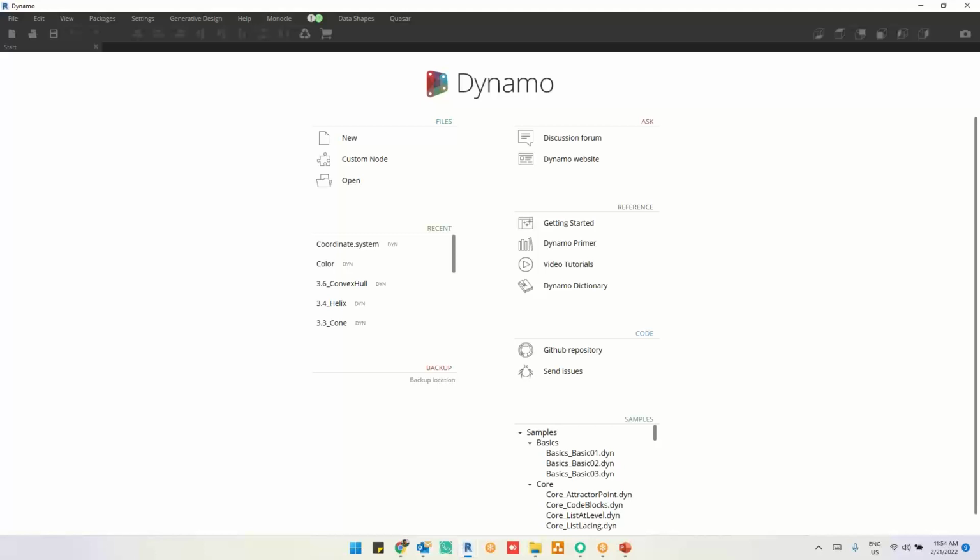No, first you have to get the coordinate system and store it somewhere, Manish. You understand? So by origin will not work when you're working on projects. The coordinate system always takes by origin. If you already have any shared coordinates, you have to use the shared coordinates somewhere in your project itself.